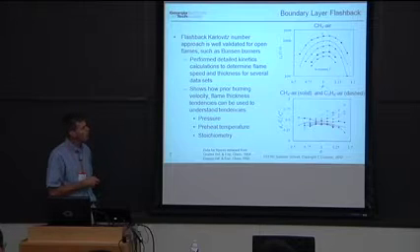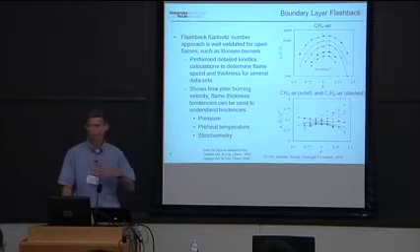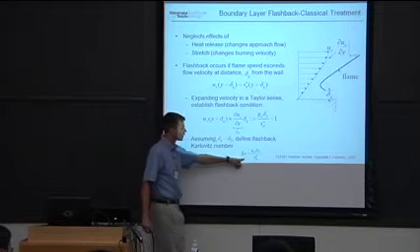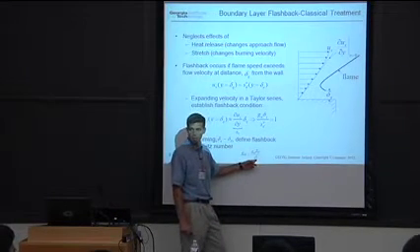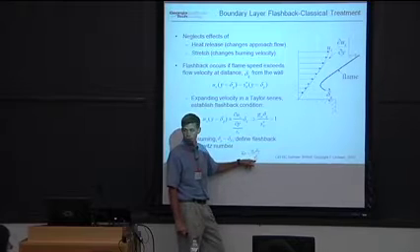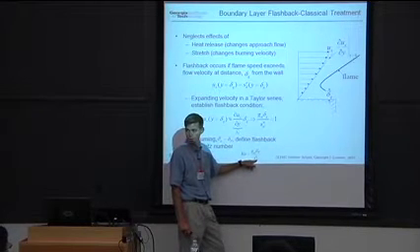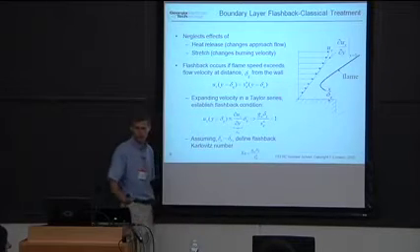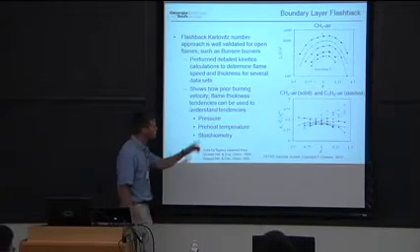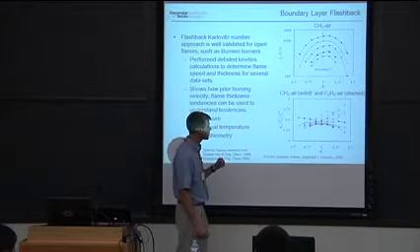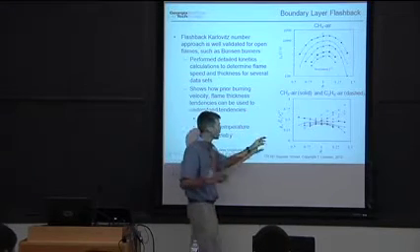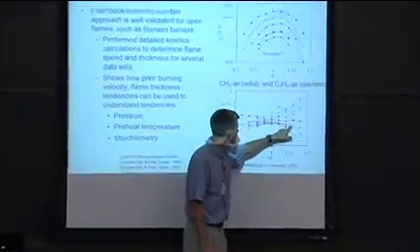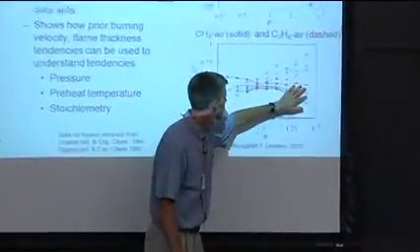But now you can go into Chemkin and run a detailed kinetics calculation. Let me back up one slide. I can calculate the flame speed, and what I'm going to calculate here are unstretched laminar flame speeds for all these mixtures. I'm also going to calculate the flame thickness, and let's just crank this through. If you run those detailed kinetics calculations, with no empiricism, and plot that Karlovitz number, you can see that all these mixtures flash back. By the way, the dark symbols are the methane data.